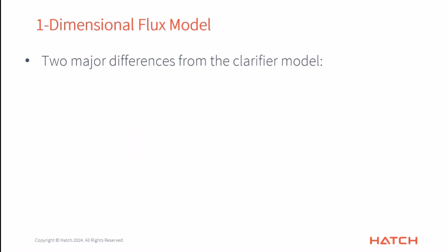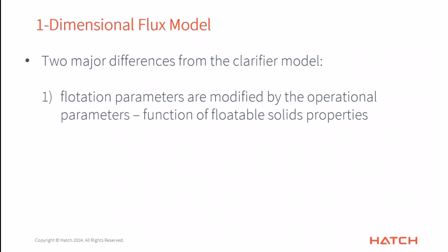Okay, so that's the part that is essentially the same as what we're doing in our clarifier models. Now I'm going to talk about two major differences from the model. One of them is that the flotation parameters themselves are modified by the operational settings. Some of the ways that solids float to the top are a function of the solids properties themselves, and those are items on the operational settings menu in